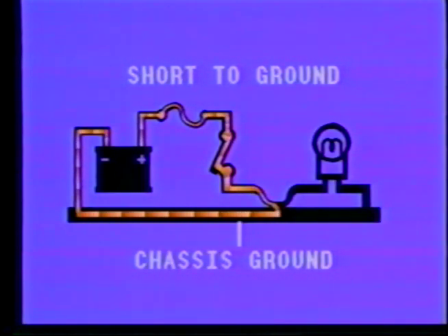If a short to ground occurs before the load device, usually the circuit protection device will blow, so that when you see them, they are already dead circuits. Fuse replacement will cause the circuit to conduct more amperage than designed for, and it'll blow the fuse again.